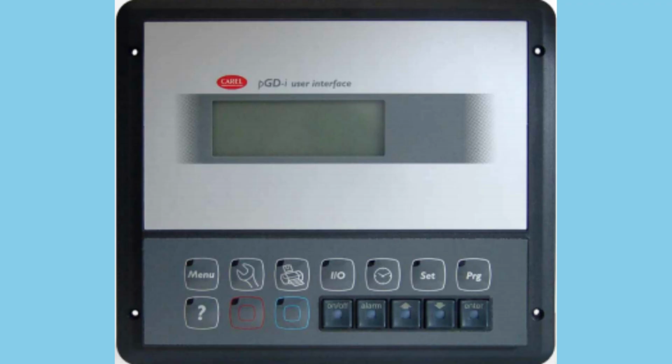Variable speed technology. Centrifugal chillers can use inlet guide vanes, IGV, or variable speed drives, VSD. While VSDs slightly reduce full load efficiency, they offer exceptional savings at part load, especially when tower water is cooler than design. A well-analyzed system can save 15 to 25% annually using drives on chillers, pumps, and tower fans.